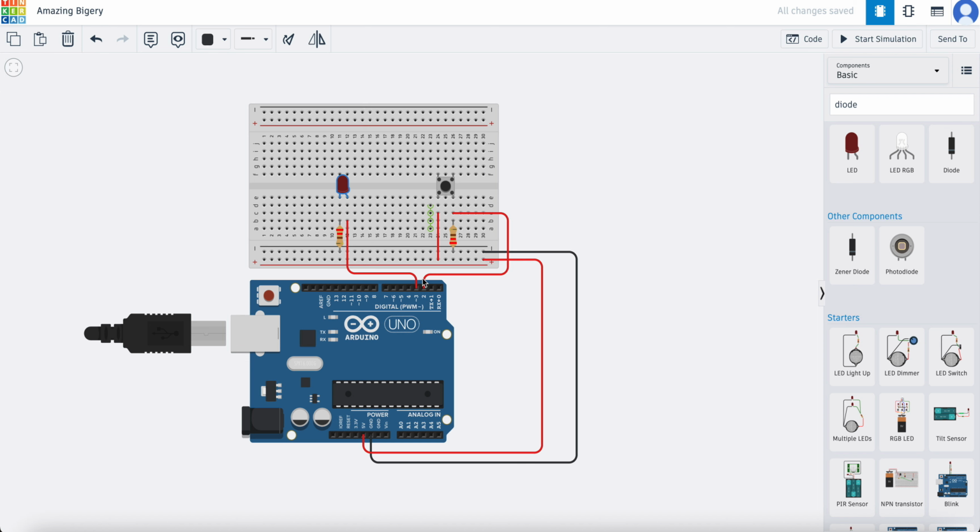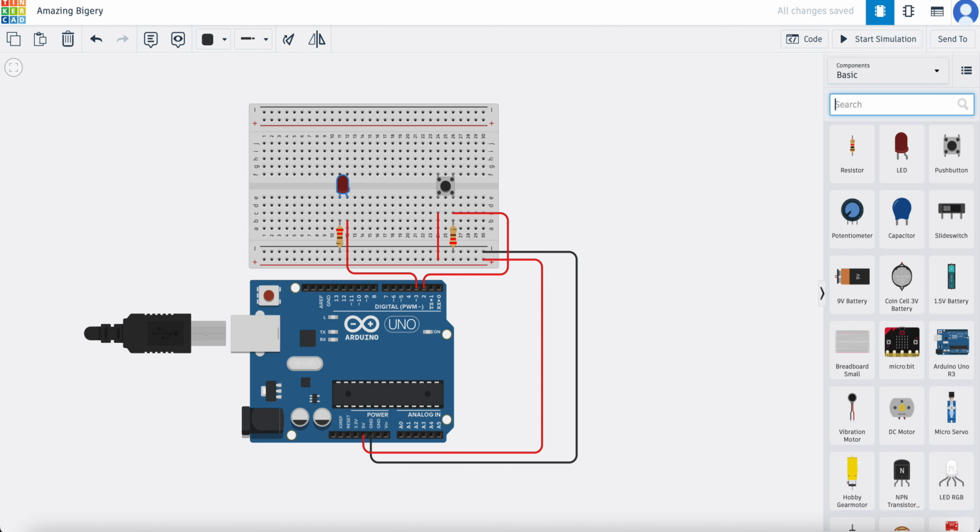They're two separate circuits. If you look here, we've got power coming out of pin number 3 into the LED, and it's coming back to ground through this resistor. The switch, power comes out, goes to the switch. It gets pulled to ground if the switch is not open or closed. That's how we get the high or low. And then it comes back here. So they are two separate circuits. However, you can add a switch which can control the LED directly.